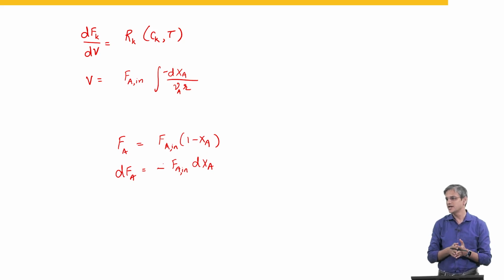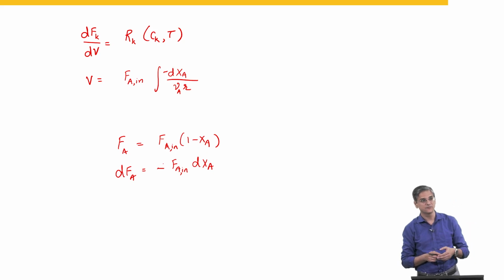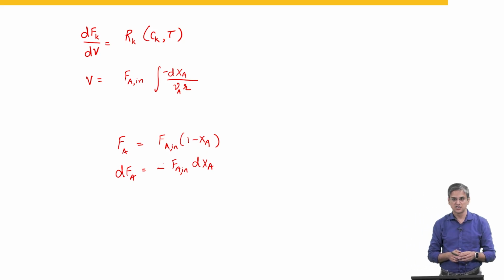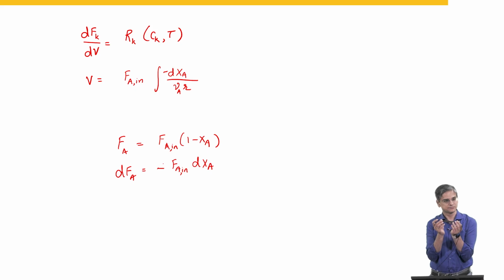So, the entire reactor is flushed with a diluent like argon, and not nitrogen in a lot of cases, because nitrogen can form nitrides or nitrates with the catalyst. So, we will pass argon, and in argon atmosphere we will heat it to the desired temperature. Okay. So, now the reactor contains argon.